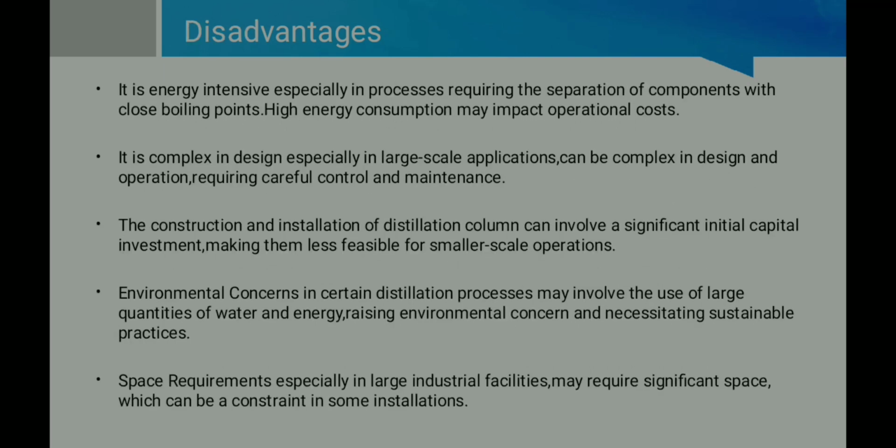Let us see a few disadvantages of a distillation column. It is energy intensive, especially in processes requiring the separation of components with close boiling points. High energy consumption may impact the operational cost. It is complex in design, especially in large-scale applications. It can be complex in design and operation too, requiring careful control and maintenance.